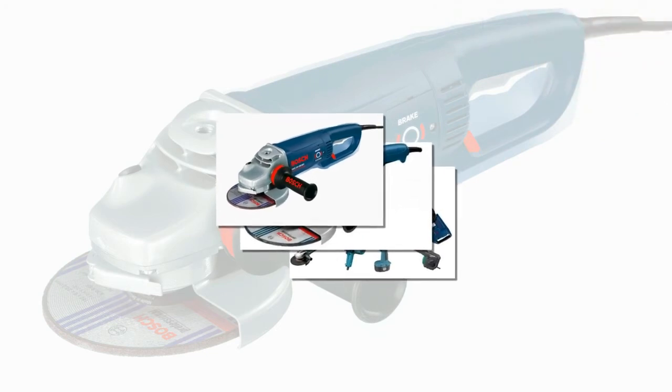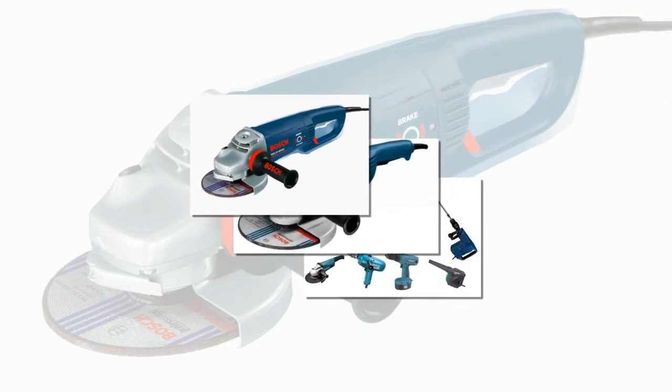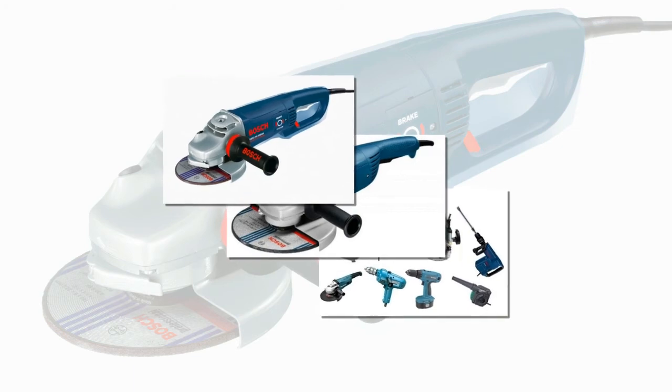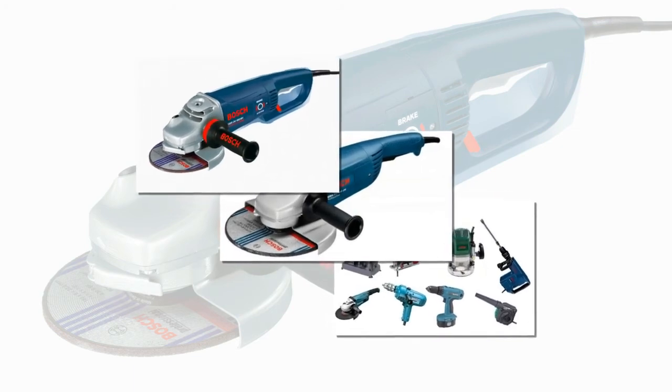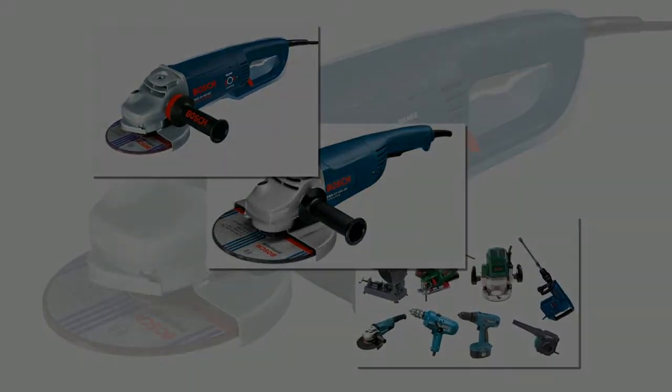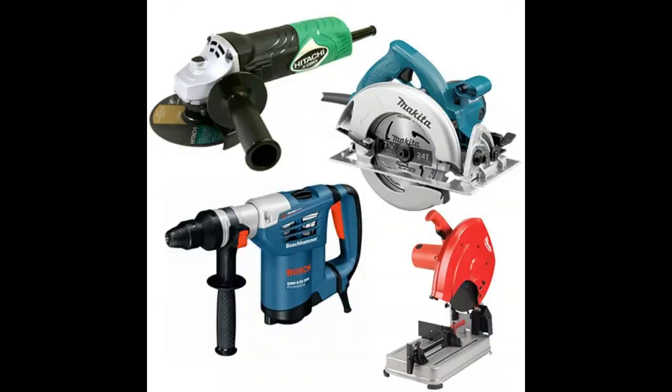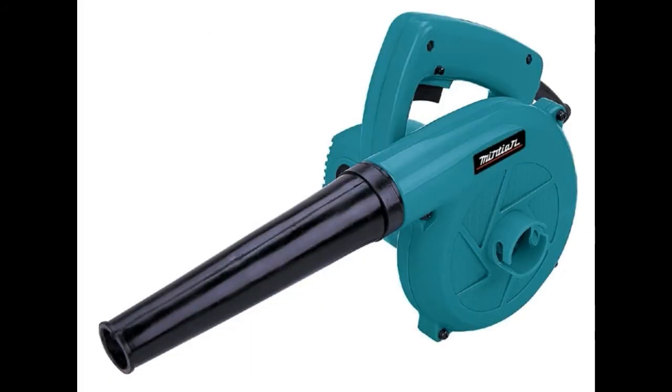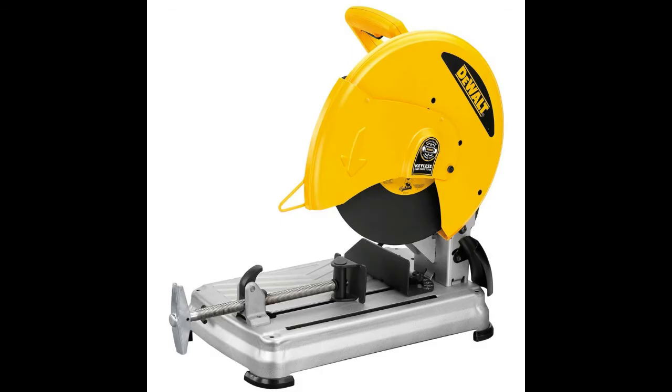Drills. The power tool version of this tool uses a motor to turn a bit. This results in the fast cutting of circular holes. Types include the stationary drill press and the portable cordless drill. Handheld drills can often be fitted with adapters so that they can drive screws, torque bolts, and even function as sanders.